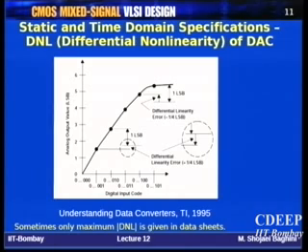But the only point is that here you will have only points in a DAC, because for every code you will get a single value. You will get just points, because in a DAC the output is a discrete value. It's a quantized discrete value. So again, same thing for DAC. For DAC now, because it is analog at the output, you look at the deviation of this step size on the Y-axis, not the X-axis. So I won't explain it again, it's the same as ADC, but just by changing the axis.